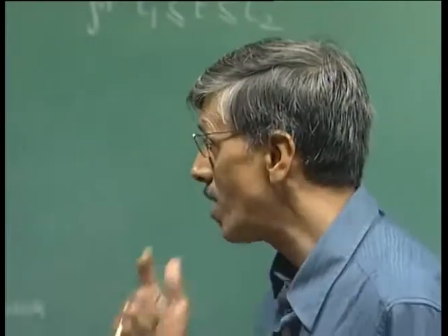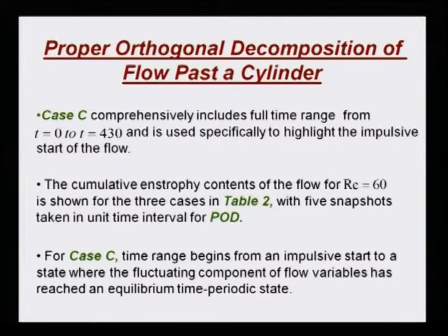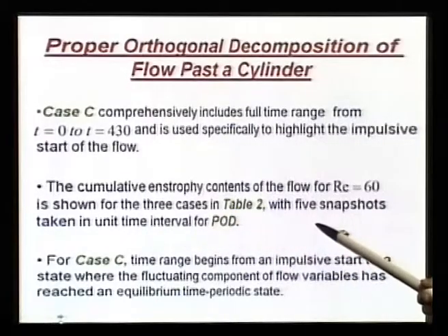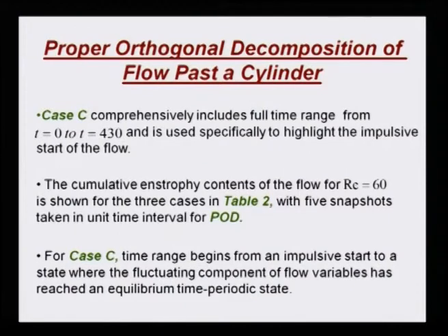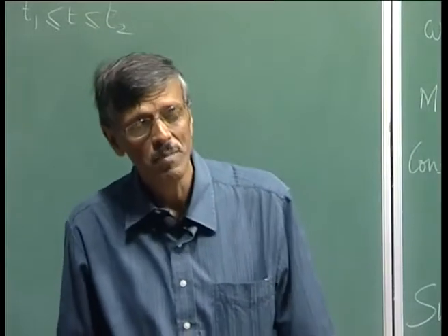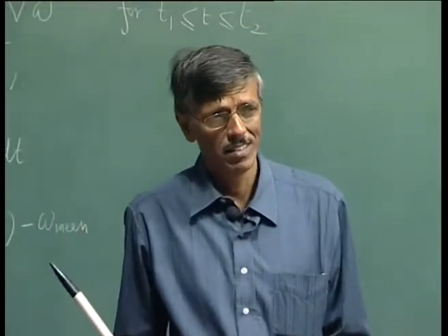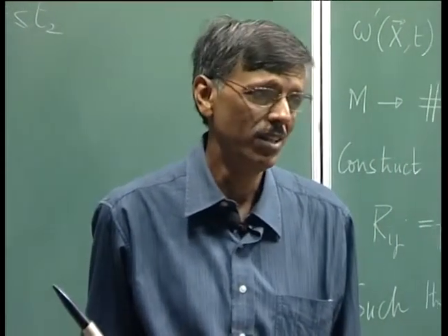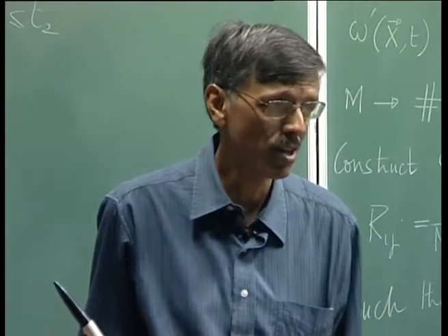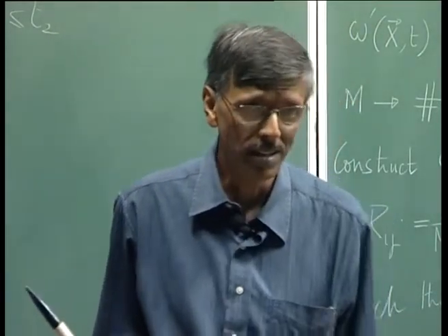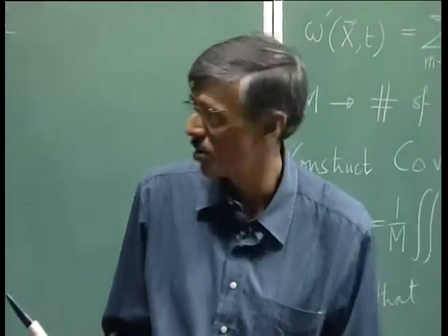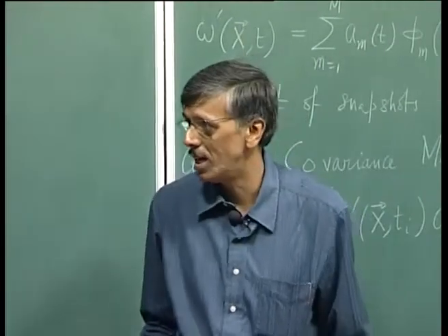So, even in recent times, we are doing PODs where we are taking about 40 snapshots in unit time interval. So, you can see, and please do understand, that taking insufficient sampling rate will always mislead you into drawing wrong conclusions. So, it is better that you go on the side of caution and have more data than less. Okay? This is something that we need to understand.